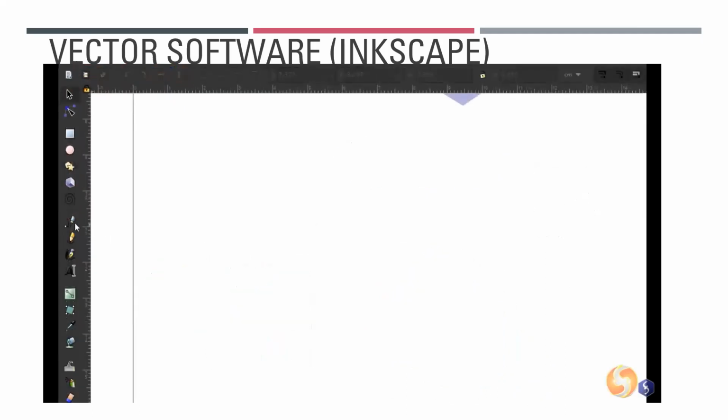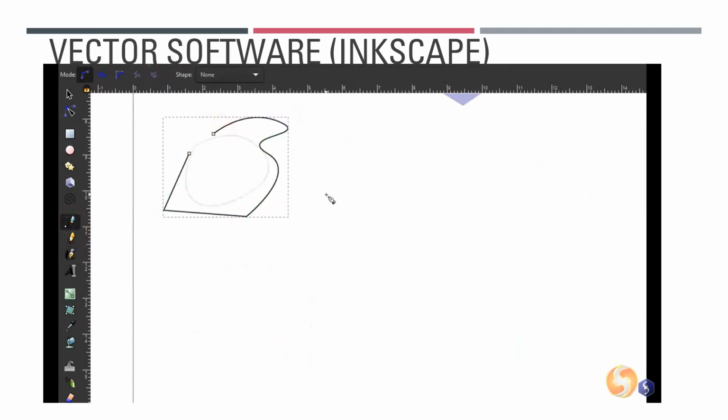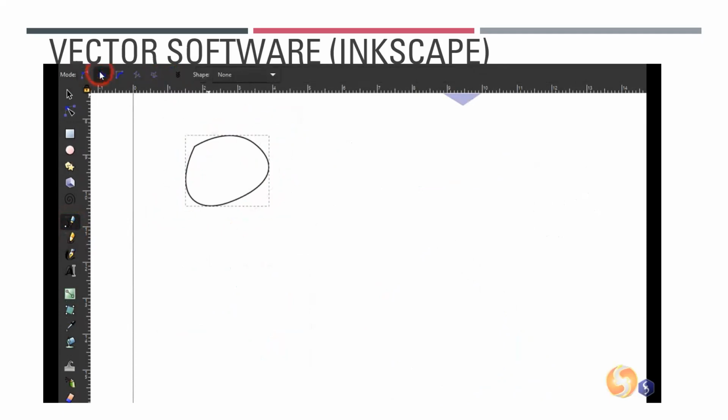You can enable other tools to realize custom shapes and paths. With the Bezier tool, click to fix several vertices and drop consecutive segments, whereas click and drag to define tangents to curves with very good precision. Then close the shape or double-click to apply. Use the options on top to change the drawing mode, such as Spiral Path to drop arcs and circles, and B-Spline to drop B-Spline curves.